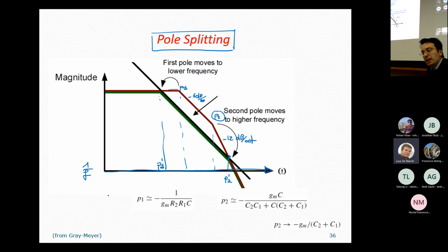Studying this transition means studying the value of I5, because basically I5 is the quantity which charges or discharges the compensation capacitance, which in turn generates the voltage drop over V drain of transistor number 2. So basically, the slew rate that we have when we apply a positive step function is the minimum value